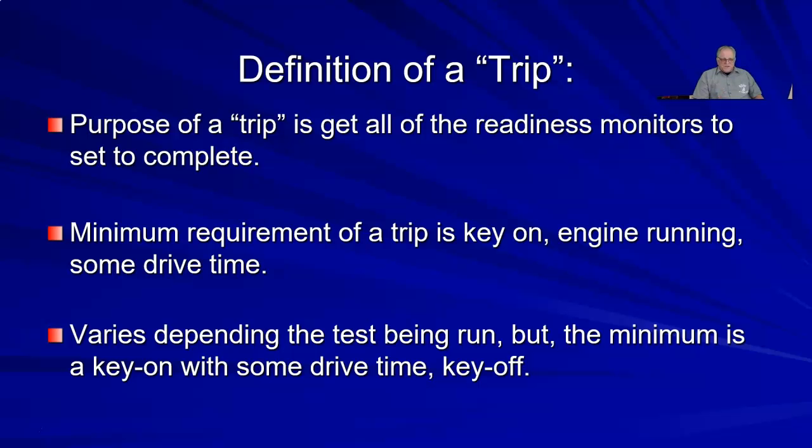There's 2 things about the trip. 1 is, what is the purpose? The purpose is to get all the readiness monitors set to complete. 2, there is a minimum requirement for the trip, and that is key on, engine running, and some drive time.